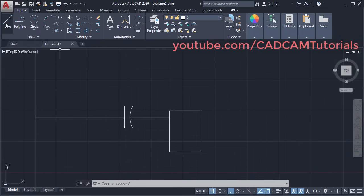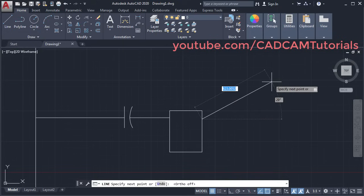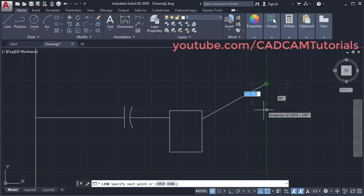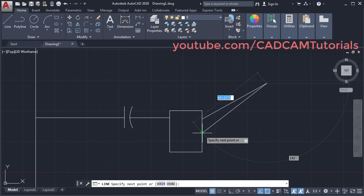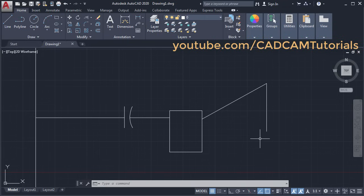Then again click on line, then take your cursor to this endpoint, take it below, click, then make ortho off, then take your cursor on this side and click. Then take your cursor to this midpoint, drag that point, click, enter.